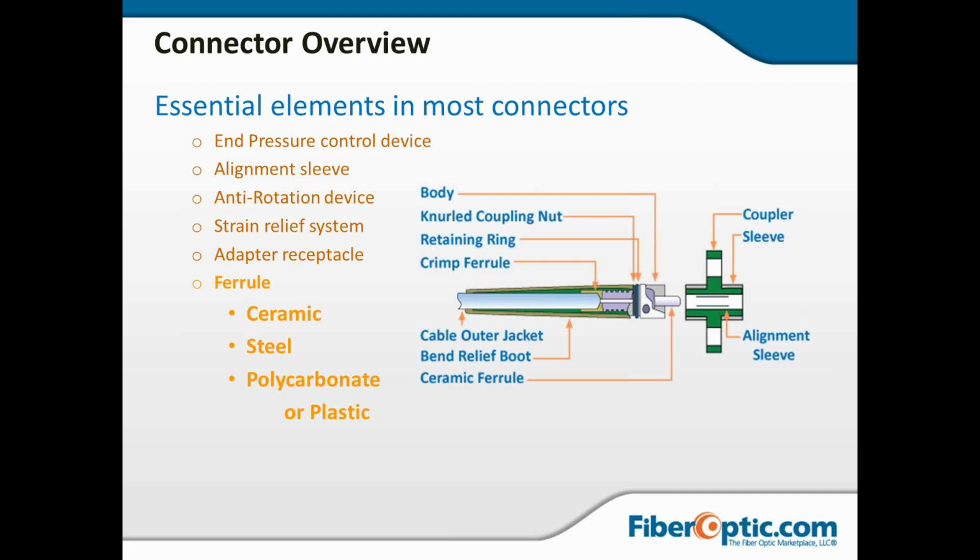In the center of it is 125 micron cladding, and within that in single mode is an 8 micron core. And the precision of these ferrules allows for those two 8 micron cores to line up perfectly and allow for the transmission of light with very low loss and very low reflection. Now, that's bordering on magic in my world.